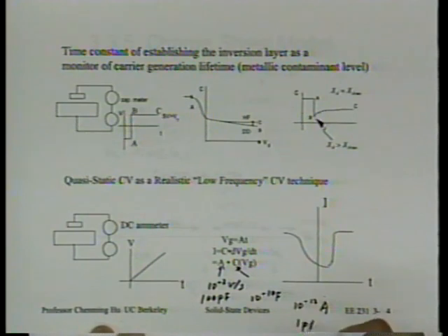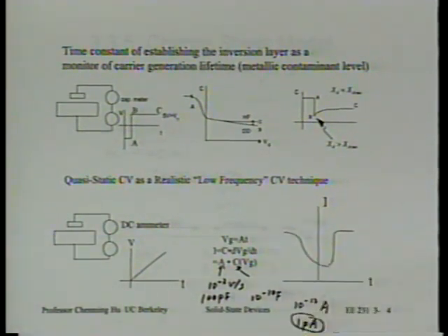It's called 1 picoamp. The ammeters we use today, can we measure picoamp? Yeah, if you're familiar with the HP meters, we can measure picoamp. The resolution is about 10 to the minus 13 ampere. If you pay extra, you can get even better. Okay. Of course, this still means that you have to be careful with the cable. You cannot have a lot of leakage in the BNC connector and things like that. All right. But routinely in the laboratory, people can set up such that they can measure this current without much problem. As a result, you will be able to measure the CV curve.